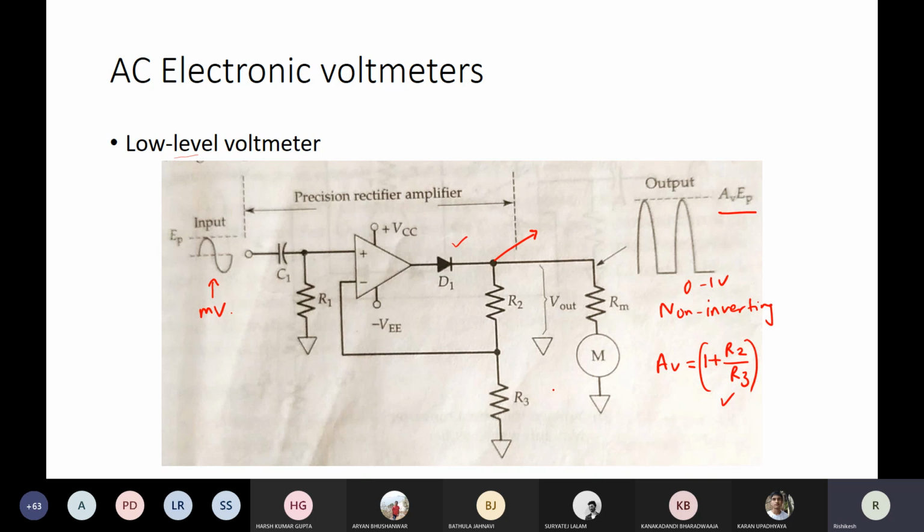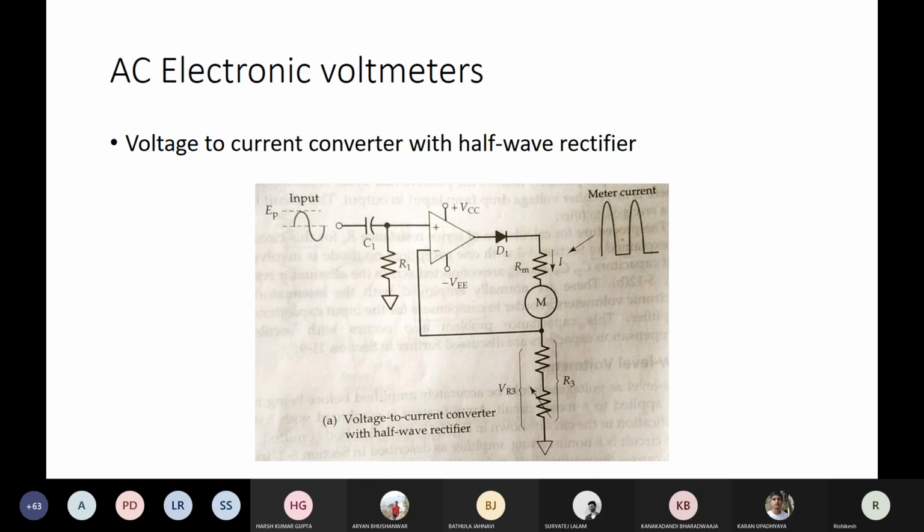Now you can appreciate that when the supply is positive and negative both with respect to 0 volts, the reference is 0 and the potential is going above and below the reference voltage, and that is why you need both power supplies. If you use only one power supply and let's say this is ground, then you will not see the negative being magnified, amplified or processed at all. So that's why this is needed, V plus and V minus.